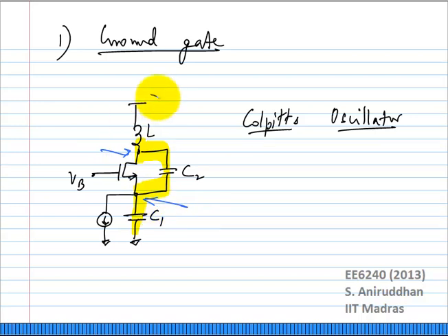Here we have connected the tank at the drain itself, so that the full amplitude of the tank appears at the drain. That is not necessary. Okay, and in fact that kind of oscillator has also been designed before. It's called a Clapp oscillator. So similarly, you can have many different configurations with certain advantages. Since, due to lack of time, we are not interested in giving a catalog of oscillators, if you are interested, I would encourage you to read the Thomas Lee textbook that we have given as a second reference. He does have a good list of oscillators which have been used before.